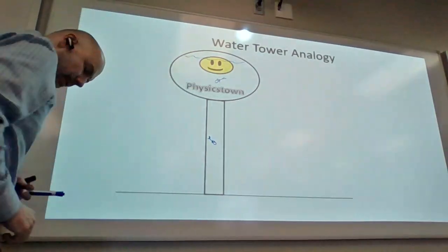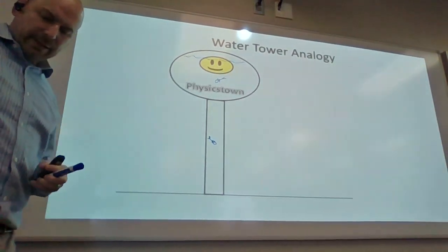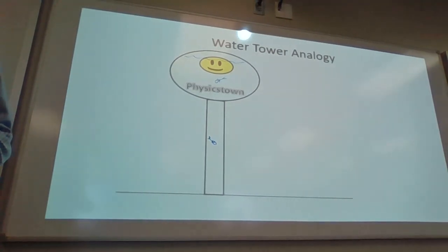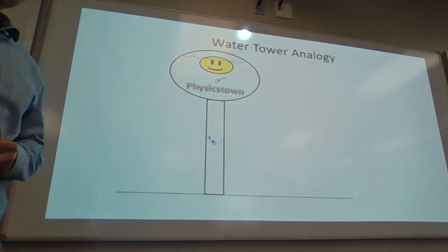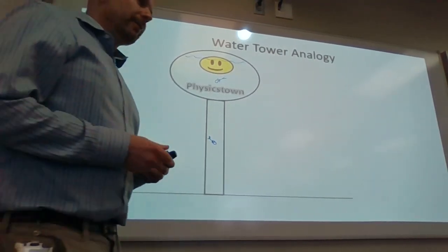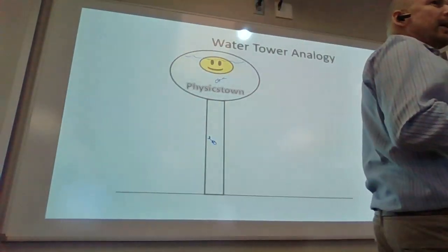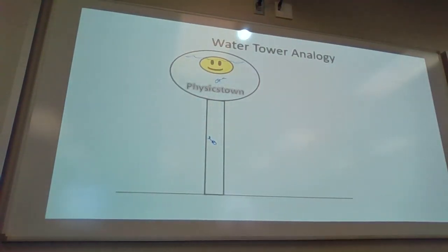Now, the other reason why this is extremely beneficial, and there's several ways. One, if the electricity went out, you still have water because it's gravity fed. Second reason, there are certain peak times during the day where we use water as a society, specifically in the evening and in the morning when people are taking showers.